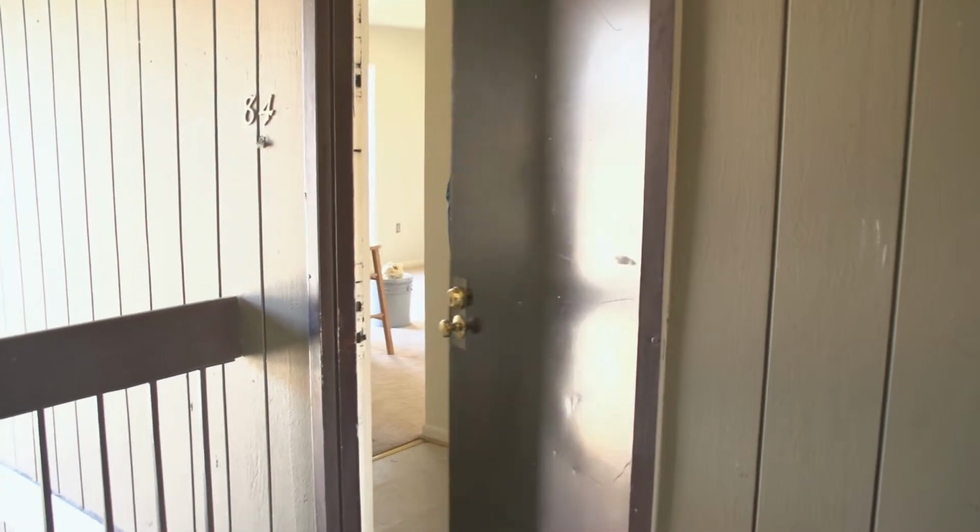At this point, we can go ahead and set up our doors and windows in the house for our CAS test. We'll start by closing all exterior doors and windows and any openings such as attic accesses or garage doors so that our exterior is sealed from our interior. We're also going to make sure that all of our interior doors are open.